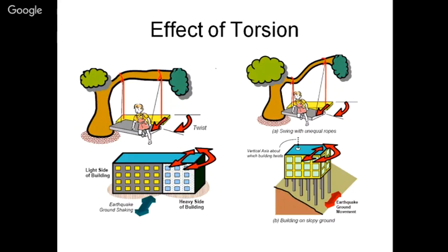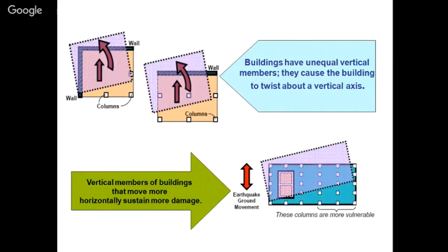In that case, we have short columns as we go up the slopes, and slender columns as we move down. The length is more, which makes the building slender on the later part. And you have the torsional kind of motion, which is vibrating in a rotation. This is the kind of rotation we have, and due to this, the column forces become critical.